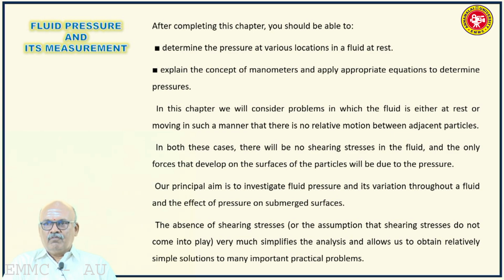The absence of shearing forces, that is the assumption that the shearing forces do not come into play, very much simplifies the analysis and allows us to obtain relatively simple solutions to many important practical problems. So even when the fluid is in motion, we assume that as there is no relative motion between the adjacent particles, the entire fluid system moves like a rigid body. So there are no shearing stresses which come into play, and it very much simplifies the analysis and allows us to obtain relatively simple solutions to many important practical problems.